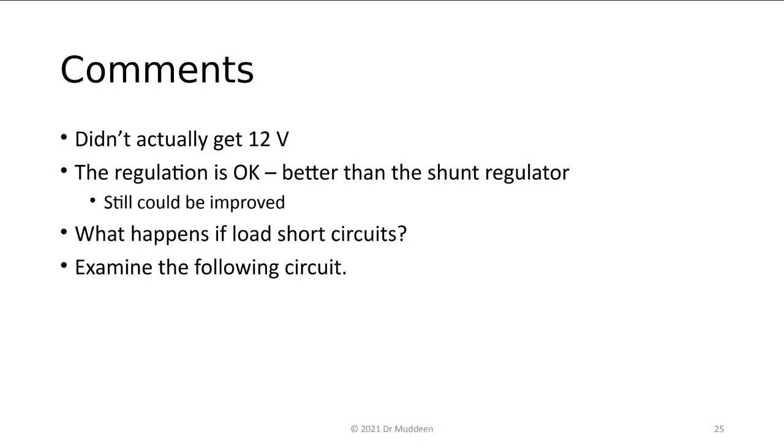For instance, take the microprocessors and logic devices that work with 3.3 volts. If somebody told you they needed a 3.3 volt supply to power some digital electronics, and you come back and say, I did it, but it's actually giving me 3.6, or 4, you're going to run into problems, because 3.3 volt devices cannot work with more than 3.3 volts.